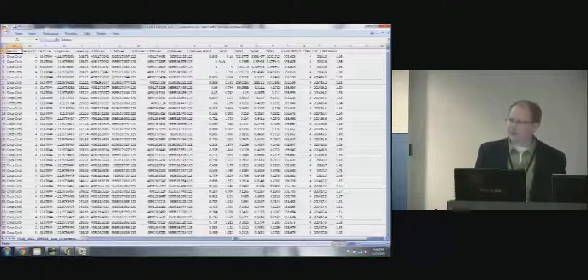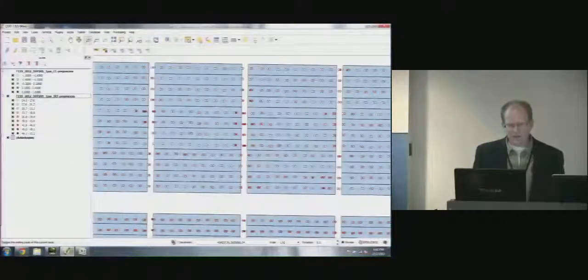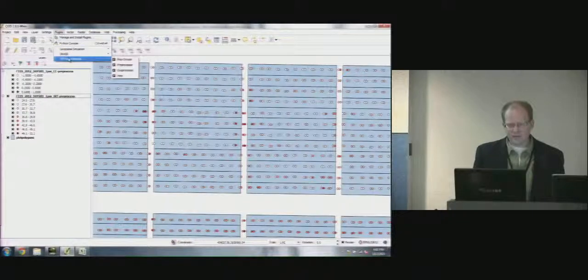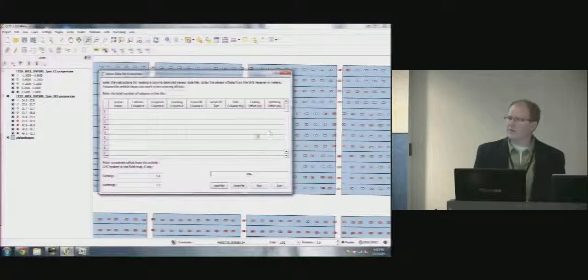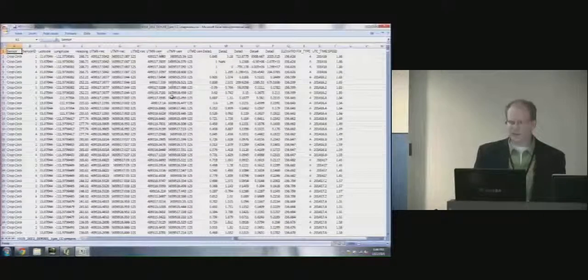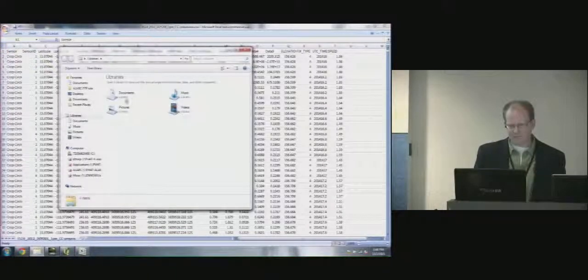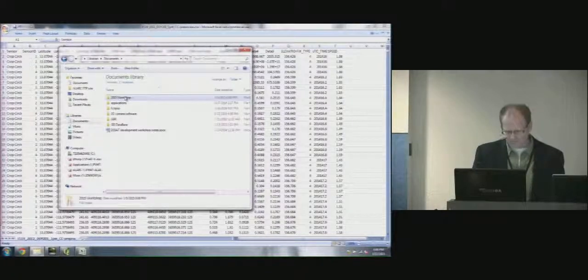Then we have to use the easting and northing values that we put in here that give the number of meters between the receiver and the actual sensor position. And from that, using trigonometric functions, we can calculate the UTM X and Y of the sensor. Just to be absolutely clear, I'll show this slide from my talk earlier this morning.